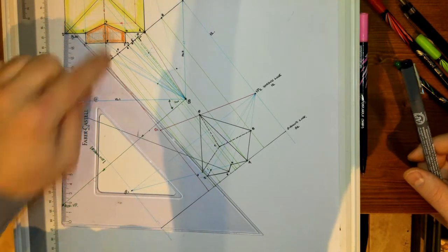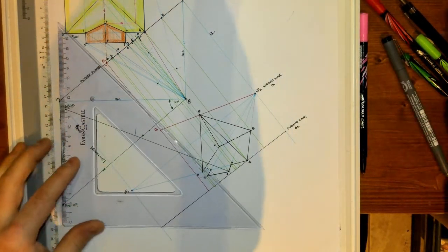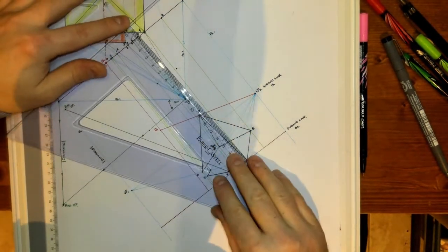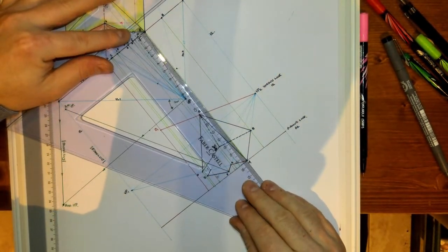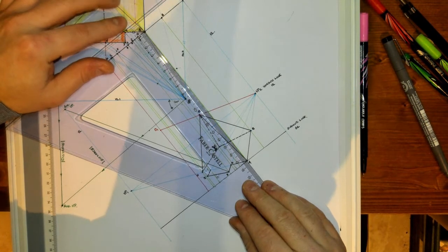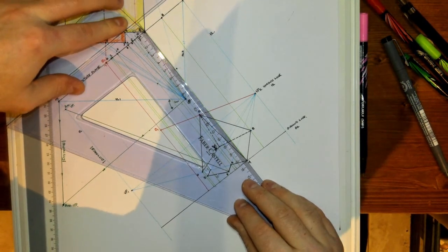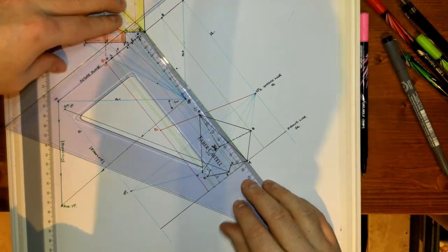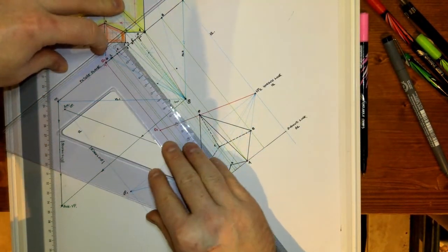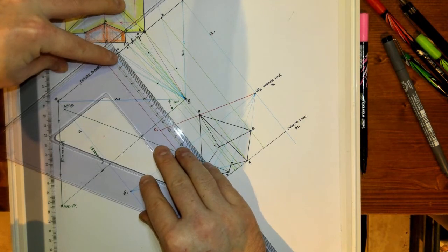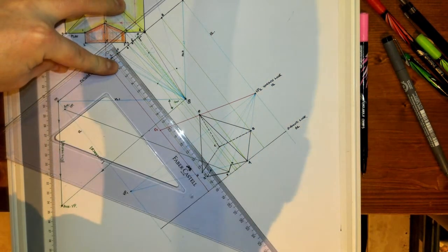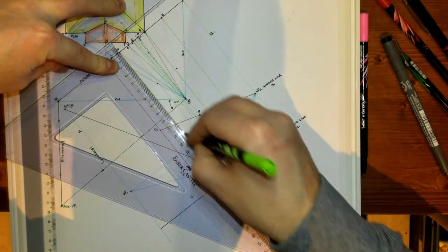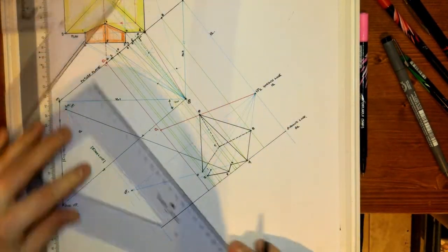Now, point 5, we need to bring that one down, because it didn't line up accidentally with anything. So I again go to my line A, and I'm always consistent when I always use the same line to remeasure from when I'm doing my sliding set squares, because if we're making a mistake, we want it to be consistent, you know, because we'll be accurate with that. So I'm going to take point 5 down now, all the way down to meet the ground line.